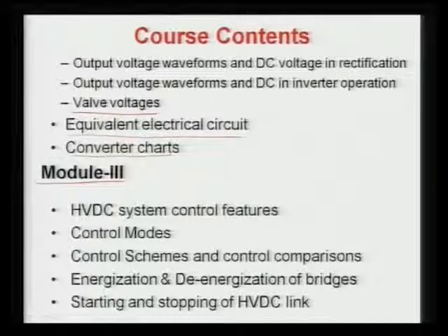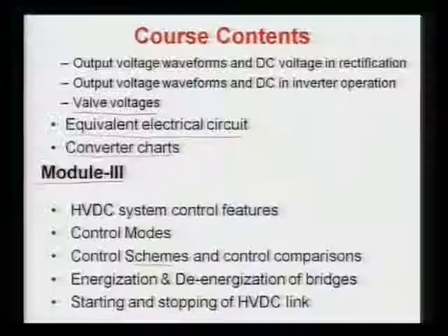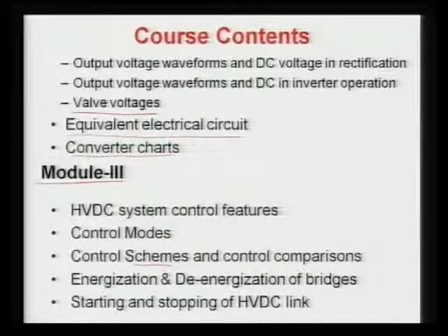We will derive the control characteristic that is suitable for HVDC transmission operation, and then we will discuss the various types of control schemes for the firing of the valves, because in HVDC this is the main thing we are doing: generating the gate pulses to turn on your valves or thyristors. Then we will see comparisons of the various schemes suggested by various inventors, and we will see which are the bad and which are the good. We can say we are going for the merits and demerits of the various control schemes.